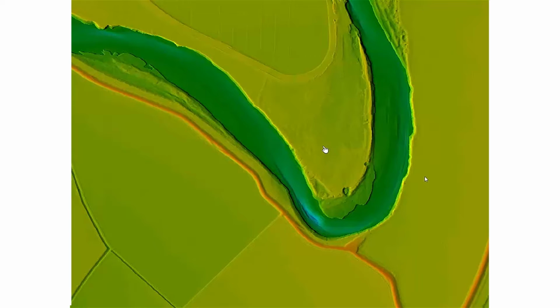So what we're looking at here is a DEM, or a digital elevation model. This particular digital elevation model came from the California Delta. It's actually a very high resolution DEM, and a lot of times, when you have a river channel like this, the surface water elevation is what's sampled in the DEM. However, in this case, the LiDAR was able to capture the river bathymetry below that water surface elevation, so there's no need to have a 1D component of the model representing the channel. So in this case, we're going to model the whole area using exclusively 2D. I'm just going to quickly go through the steps involved in creating a 2D model.